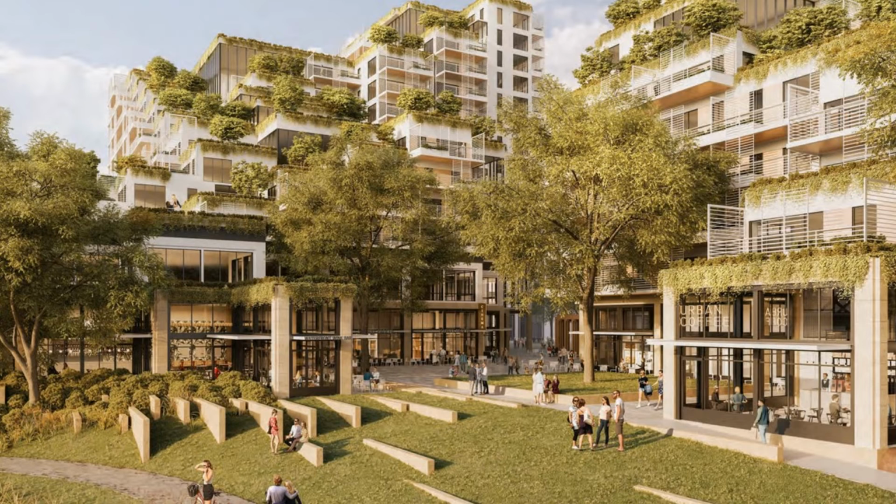And you'll see that in historic architecture, in the downtown core of Los Angeles. Any major city you go to, you'll see these double height spaces on the ground level and then more typical residential ceiling heights above. So that's a way of creating spaces that are to scale with the activity and the use of that space.